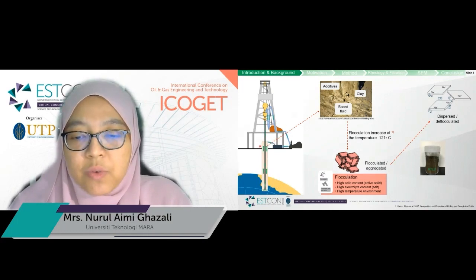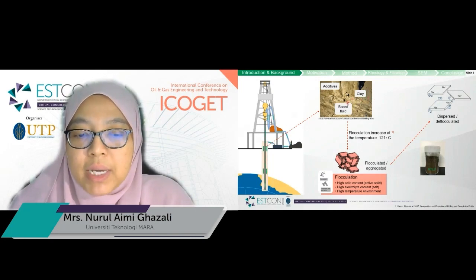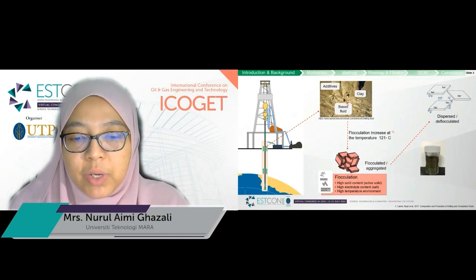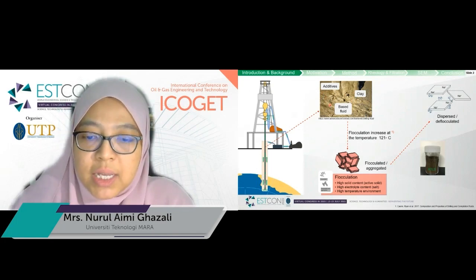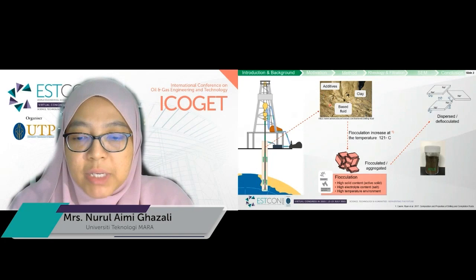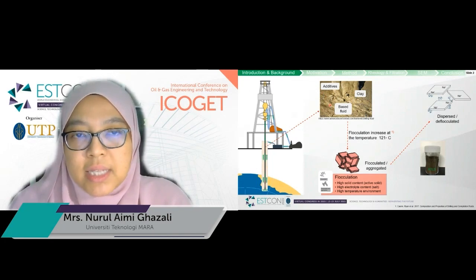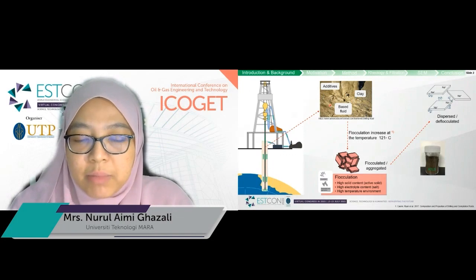Our research is focusing on water-based drilling fluid, which mainly comprises water as the base fluid, bentonite from the clay group, and additives. Due to the high surface area of bentonite with a negative zeta potential, it is a stable colloidal suspension in water. But dealing with bentonite is very crucial since it is sensitive to the formation environment.